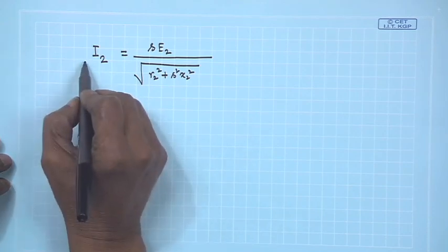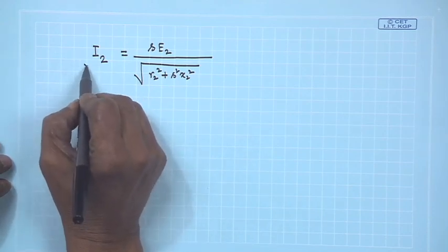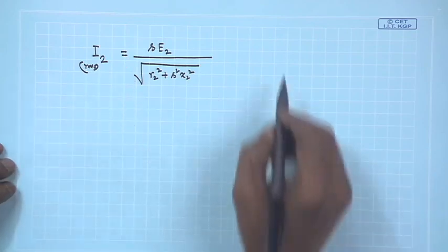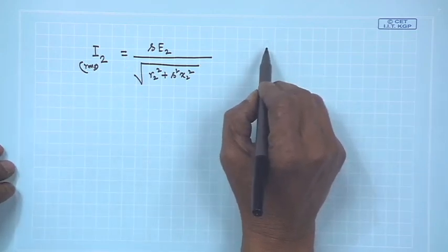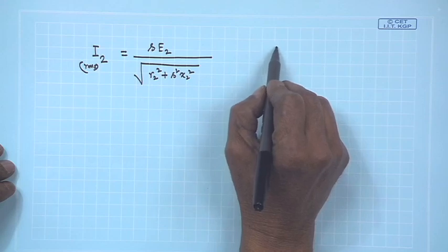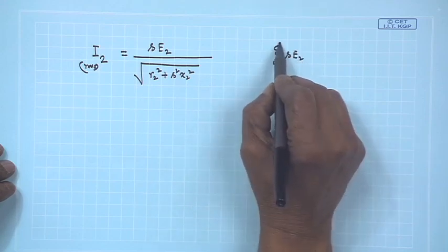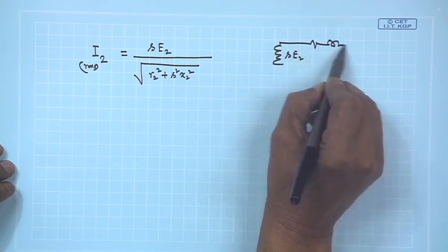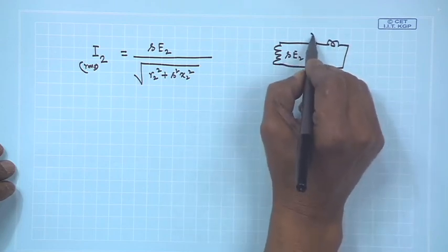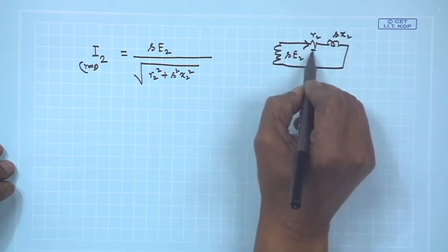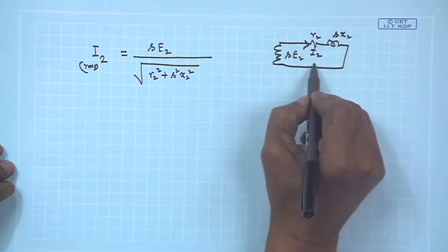And this is the RMS value of the actual rotor current. So, the rotor circuit was like this: there was a voltage source S E 2, and it is R 2, and this is S into X 2, and this is the current I am talking about. Frequency here is S f.